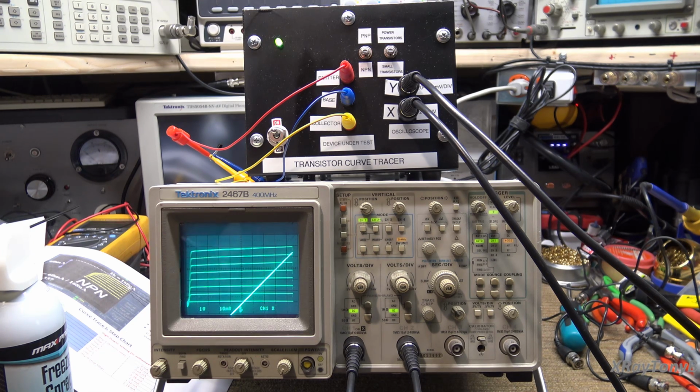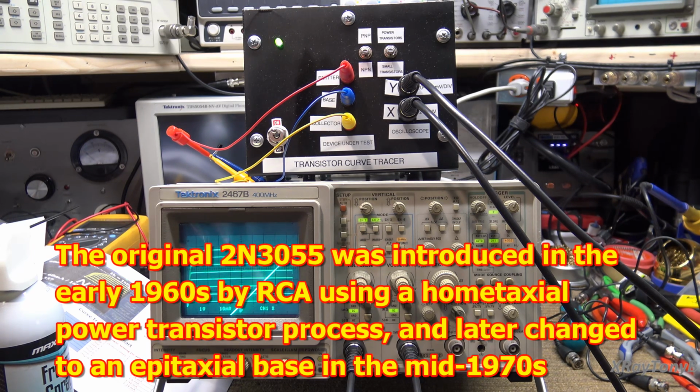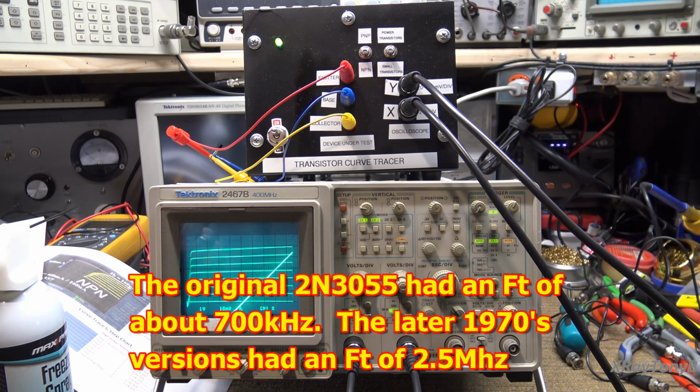Now, some transistors have very high transition frequencies, even up into the hundreds of megahertz. But some have lower frequencies, like some of the early silicon transistors, like the original very first 2N3055 that came out. Some of them only had less than a 1 megahertz transition frequency. And even the newer ones only had a couple of megahertz.